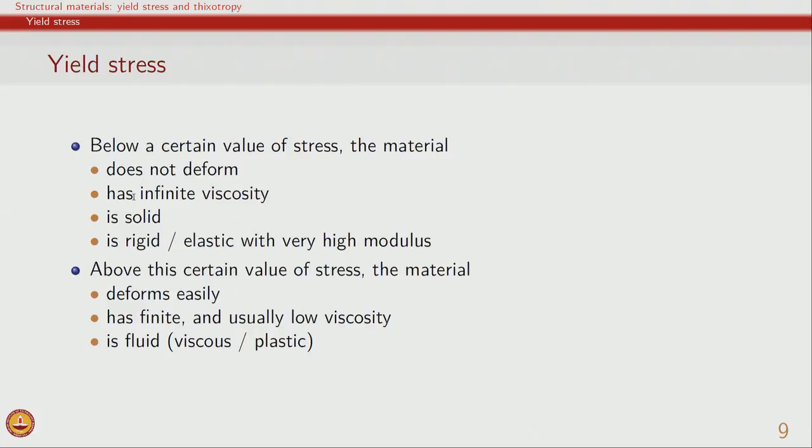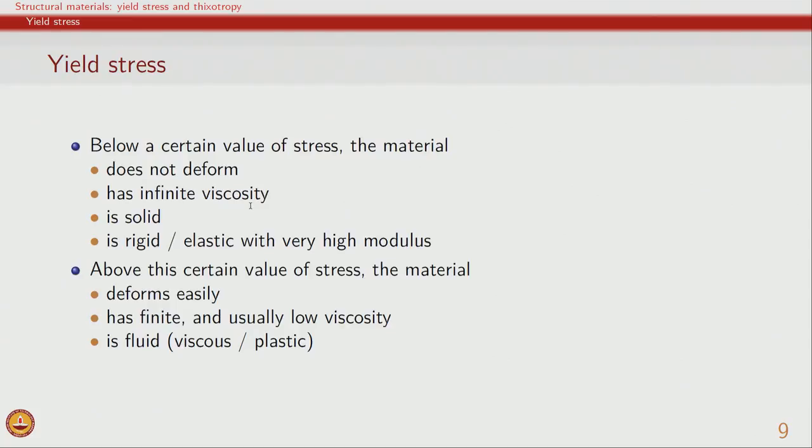It has a very high viscosity when the material is just scooped out, because it is a solid material, and then when we start spreading it, it spreads very easily. So, therefore, its viscosity decreases beyond a yield point. So, we can talk of many of these materials which we use in the kitchen as yield stress materials, that below a certain value of stress they would pretty much be like a solid. Butter also, for example, will remain like a solid block, but if we use a knife to spread it, it can be spread, and therefore, it has a finite viscosity.